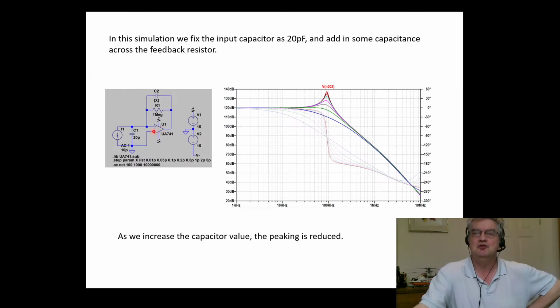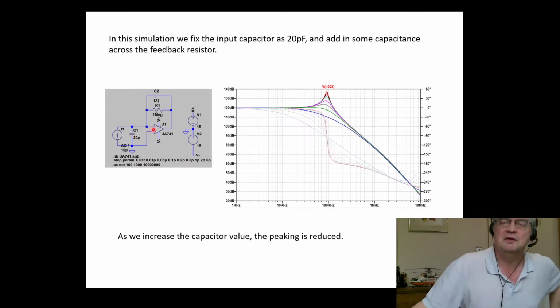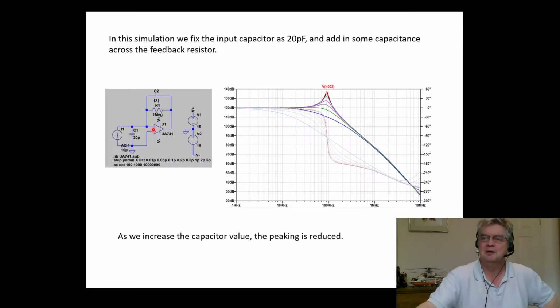Then this capacitance starts to come into the circuit and can have an impact, and we can see from the previous graphs that it led to peaking in the response, as we started to generate a little bit of instability and resonance due to this being a second order function, and we'll talk about that going forward in a little bit as well.